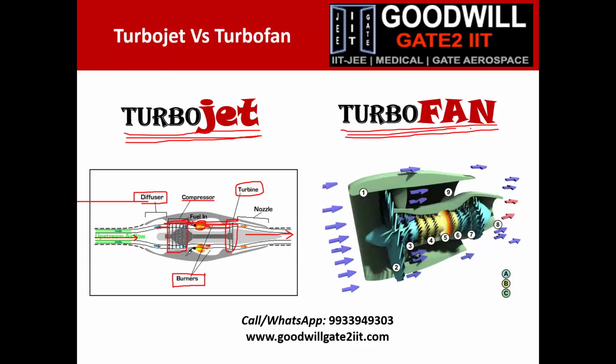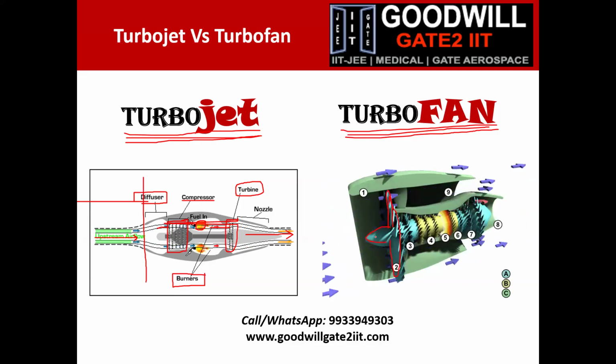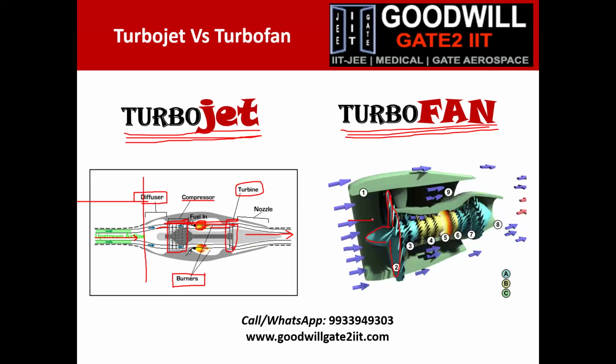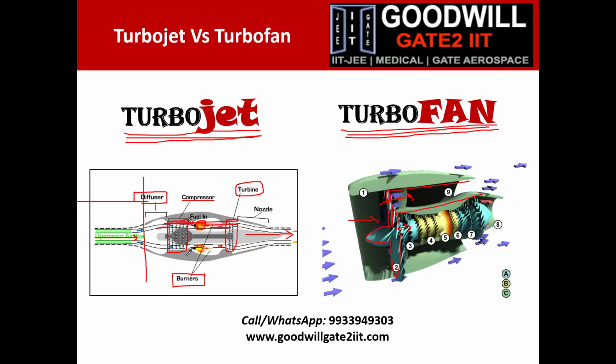When it comes to turbofan engines, there's a slight variation. Before entering this portion of the diffuser, you install a fan. You can see a big fan at the entry, right? In a turbojet, this fan is not present. What this fan does is divide your air into two streams. One, if you see this portion, is basically a cold stream, and the other amount of air enters inside, which is known as the core engine.